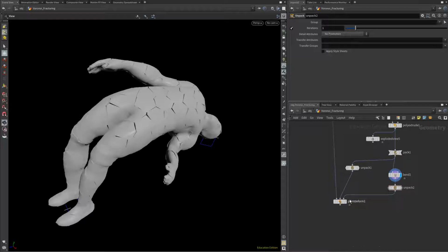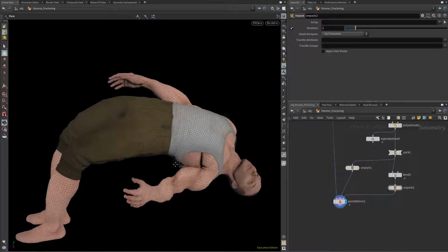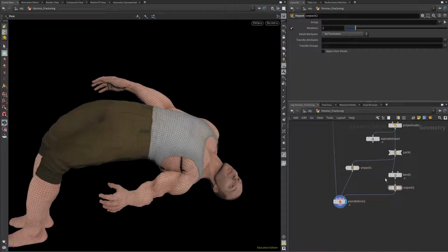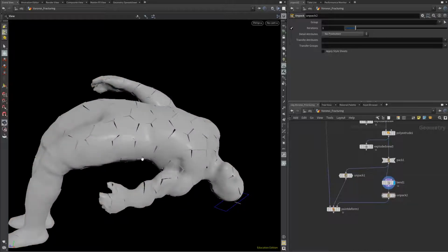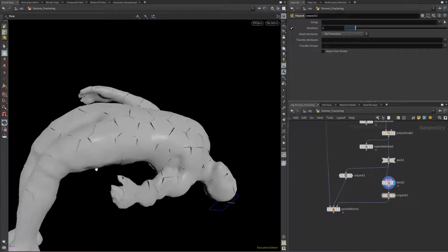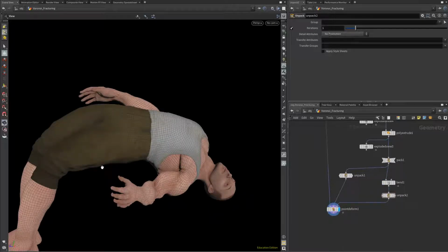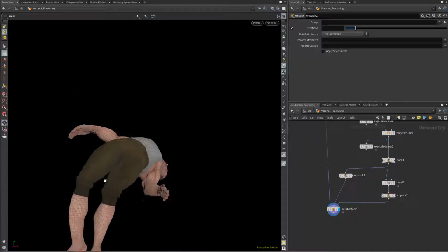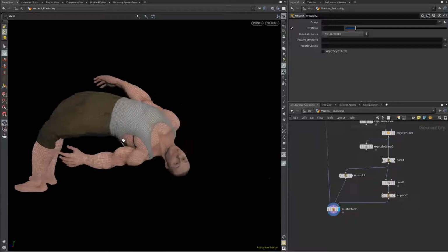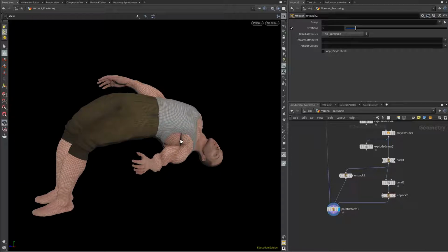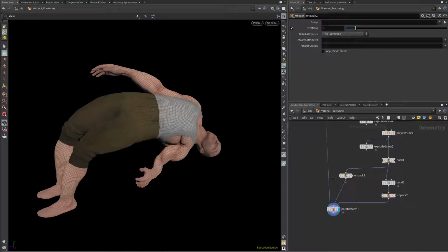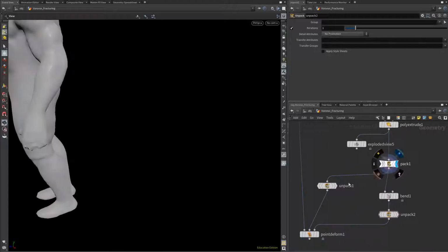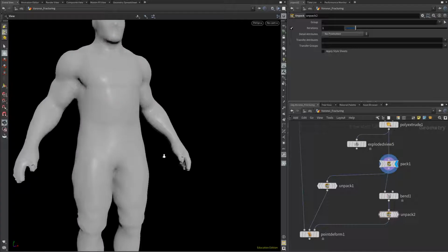So I will often take something like a deforming character and break that into lots of pieces at a rest frame, and then I will point deform those fractured pieces with the actual character animation to get a decent collider object. There are other techniques to do that sort of thing besides a Voronoi fracture. We'll discuss convex decomposition later, but just wanted to mention that as another quick use case for a reasonable Voronoi fracture in production.